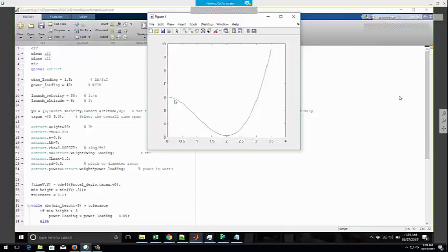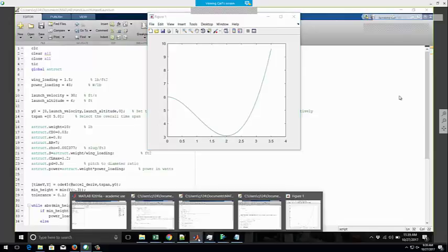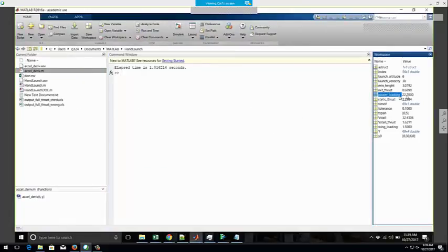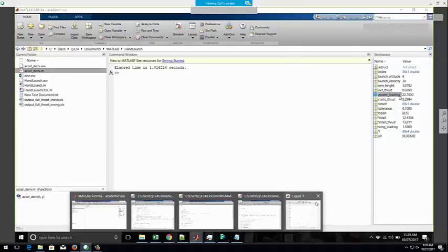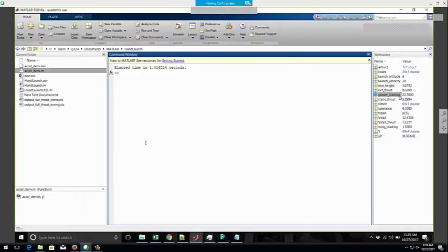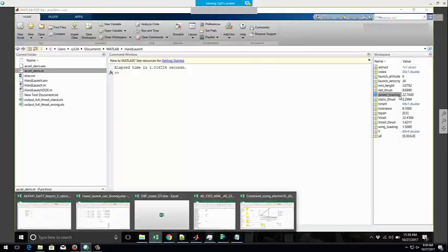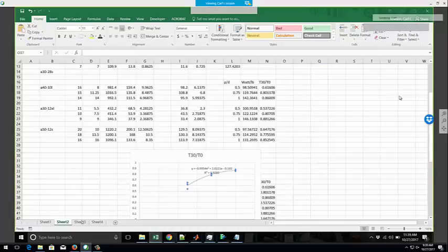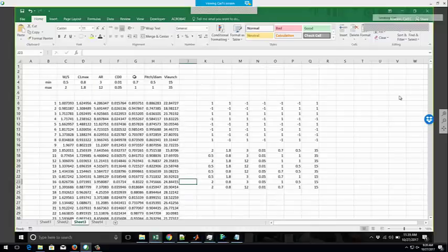But keep this in mind: we're extremely sensitive to the hand launch. And I would strongly discourage teams from picking propulsion systems that are too weak. You can run into problems very, very quickly. If you assume I can throw really, really hard, then suddenly the hand launch doesn't matter. But if you have one weak throw, your airplane is going to hit the ground. And that sensitivity is very, very strong. And if you get even weaker, now you need ridiculous amounts of power.